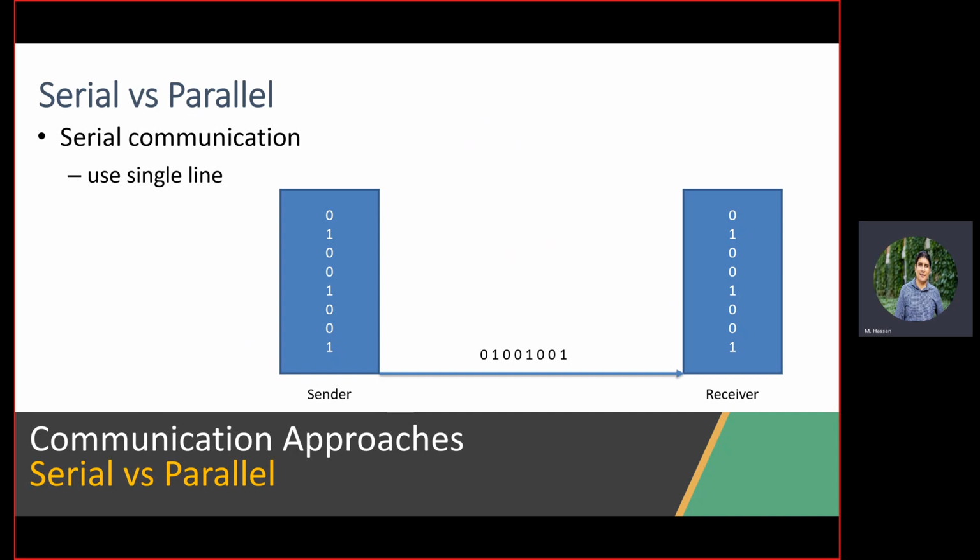So there are two factors that control the bandwidth: the speed of the transmission, where we said serial can be better, but also the rate of the transmission, where in parallel, even if you operate at a lower speed, I'm able to send multiple bits at a time. So it's not really a winning specification for either parallel or serial. It depends on the rate you are sending at and how fast you can really run your parallel bus, right? This makes sense.